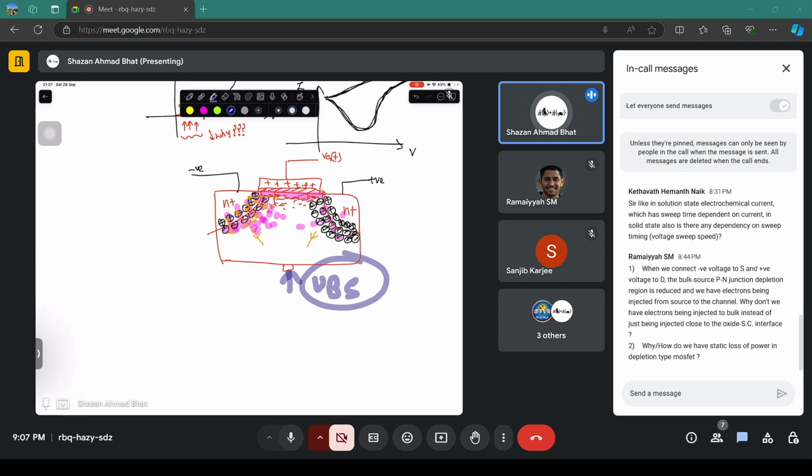Once the gate voltage induces the channel, conduction can take place. But once the gate voltage is removed, the conduction should stop. If there are already carriers present in the channel, the current is going to flow through the drain to source pathway without the gate voltage. That is going to cause the I squared R losses, and that's going to heat up the device even.